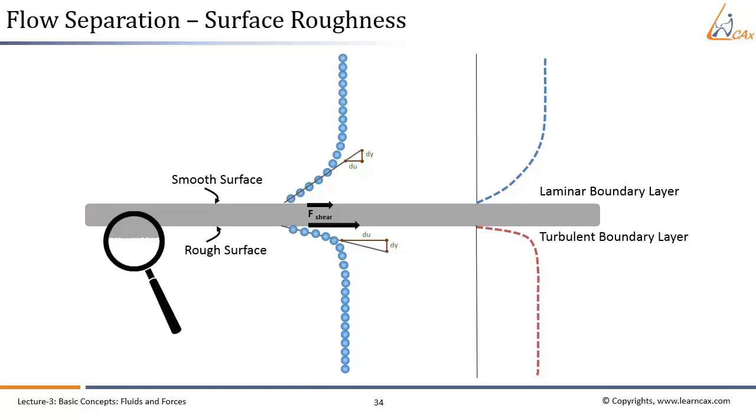The surface roughness makes the boundary layer turbulent. In a laminar boundary layer, any exchange of mass or momentum takes place only between adjacent layers on a microscopic scale, which is not visible to the eye. A turbulent boundary layer, on the other hand, is marked by mixing across several layers of it. Packets of fluid may be seen moving across.